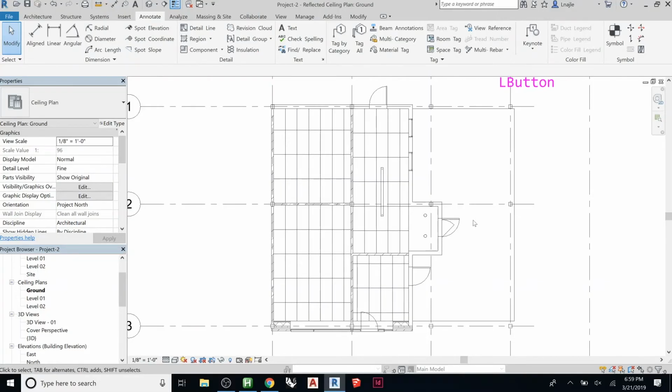But you want to be careful because they'll model all the detail possible in it, so the file will be super huge, and it will put a ton of junk into the file that you don't really need. So what you can do is download their model, open it separately and simplify it down, or you could just mass something around it that's the same size, save that as your own Revit family, and then bring that in.